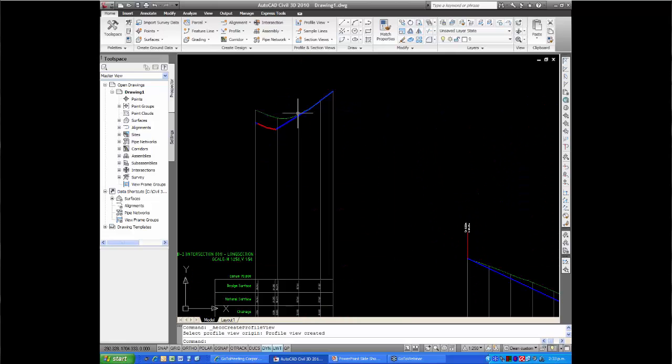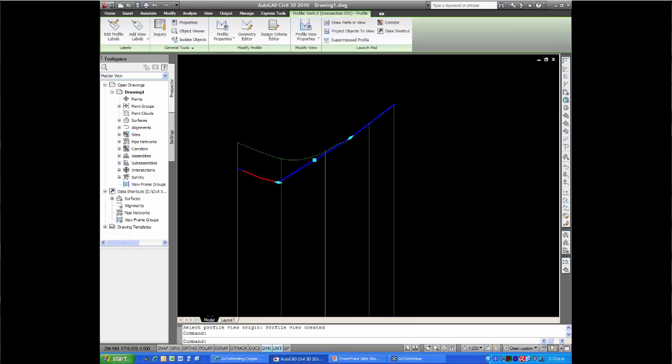By default, your screens are still catching up, I expect, but by default, Civil 3D puts in a straight line segment between the two intersecting roads for the curb return. That is to say, it doesn't put any curves in the vertical alignment of the curb return. This is something I talked to them about when they were first developing or brought out Civil 3D as a beta version, the 2010 beta version. I asked them if they could put curves in there, but they didn't do it at that stage, and they still haven't done it. So it's not a great hardship to put curves in there.